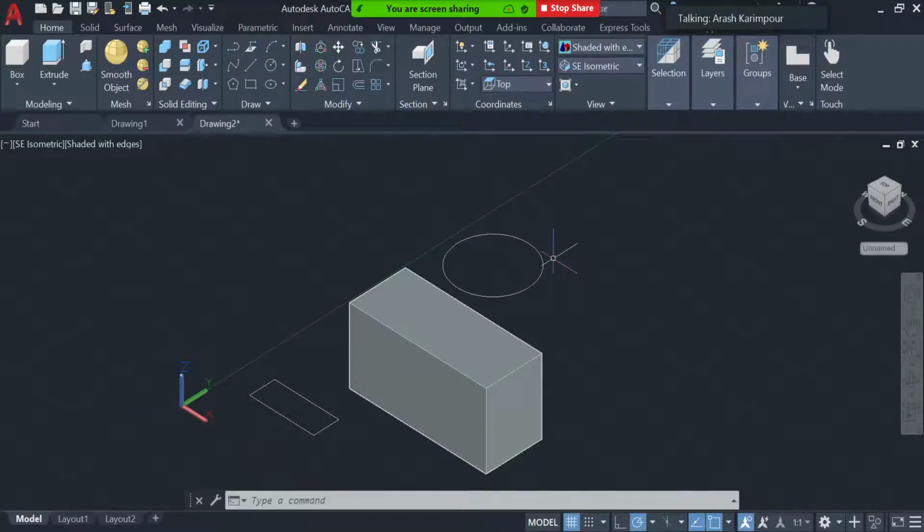One way, which I will show you later on, is that we can use a user coordinate system to do that. But for some of the very basic cases, we can come here, click on this coordinate system here, and choose wherever you want. So if I click on that and say, okay, I want my coordinate system to be on the front, it basically means rotate my coordinate system in a way that X and Y sit on the front menu.